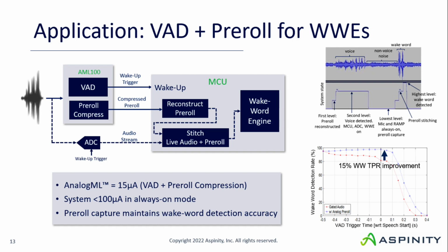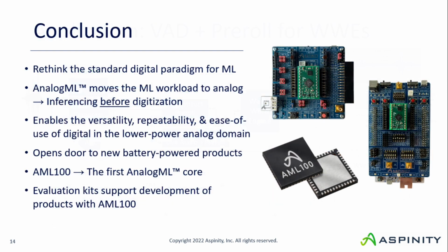So for instance, if you've got a classifier that you've developed and it requires being operated on a higher power processor, or you just have an embedded platform that you really like to work with, this cascaded wake up allows you to keep the system level power consumption down. And it maintains an average power consumption that's very low. It's typically an order of magnitude or less than the power consumption of the digital processor on its own. This allows you to start thinking about building a whole variety of new types of applications that weren't previously possible.